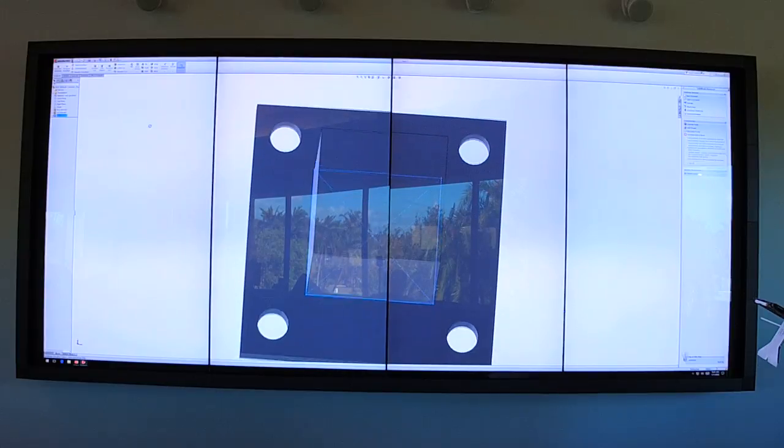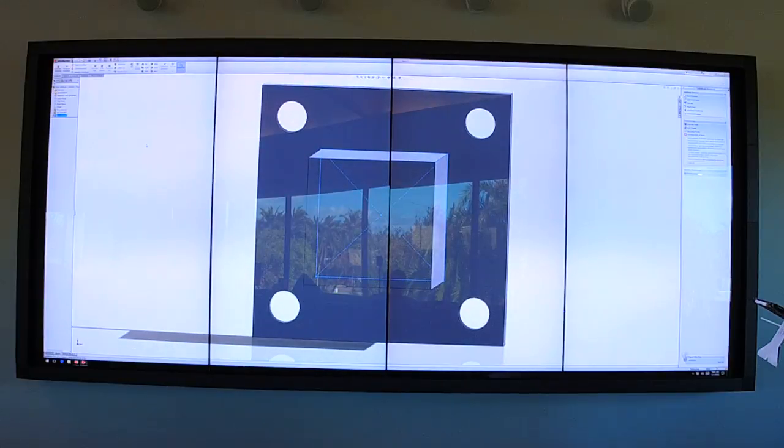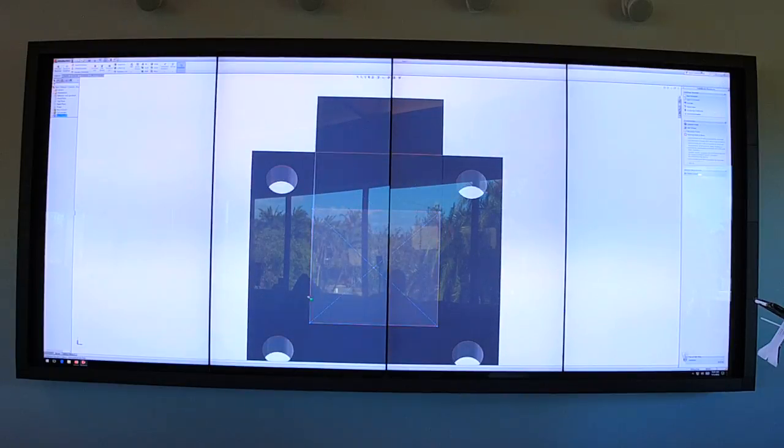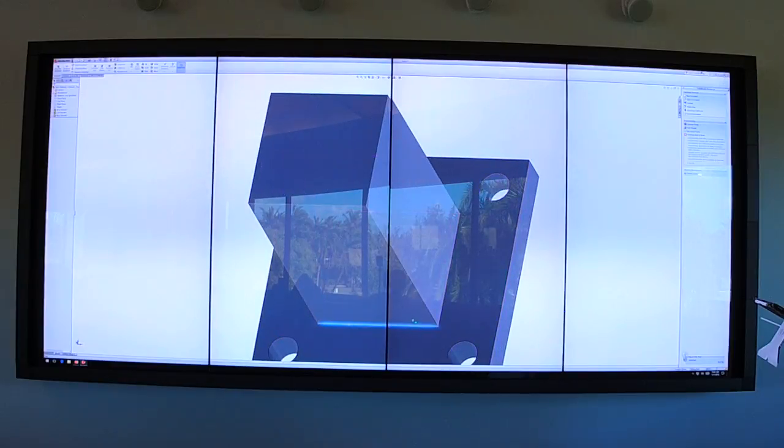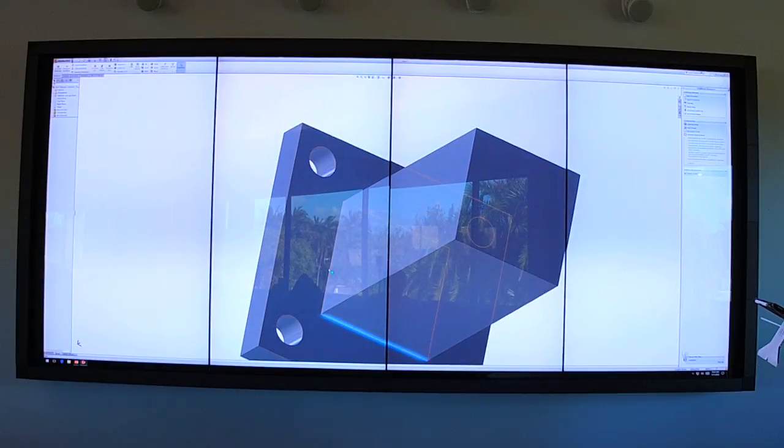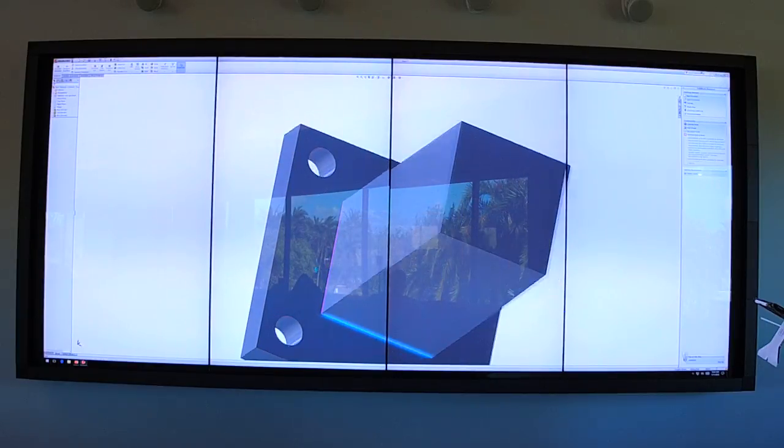So let's say I want that bottom to blend. I want it to smooth in. I want a nice curve in that. So what we do there, we select the faces. And when we talked about the edges before, this is where you can work on different edges. I can spin this around, select different edges as we go around.